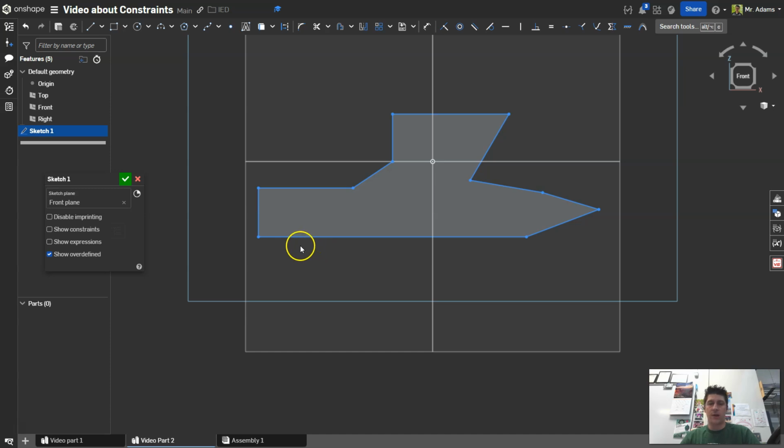So ultimately what I'm trying to build is some sort of a bracket that will be made out of metal. Okay, so we've got some relationships that we've built in on this side. Now, let's use what we've got over here and make it so that these ones on this other side match. And to do that, I'm going to use the parallel constraint. So up here in my menu, this is the parallel option. I want this line to be parallel with this line.